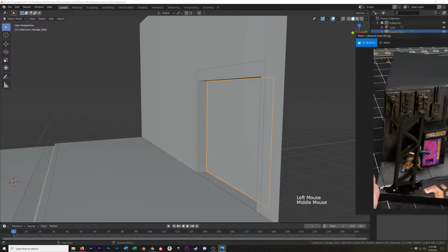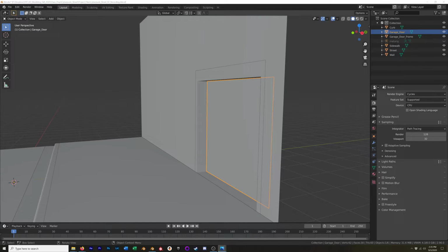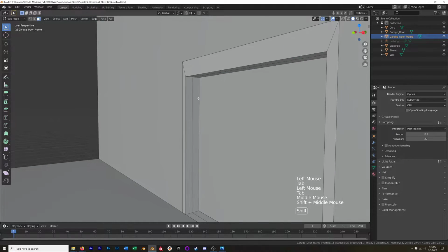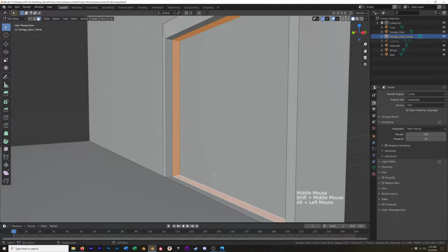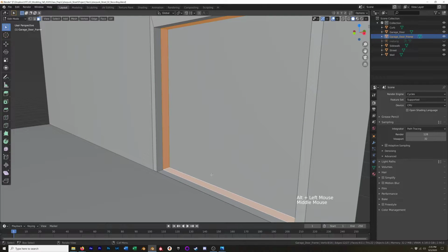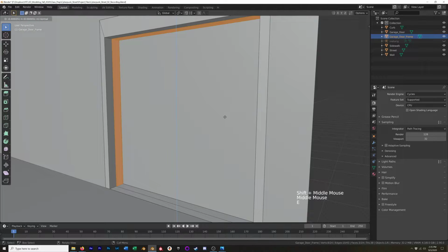And we are eventually going to add this kind of corrugated texture to it, so it's going to have some depth to it. I want to make sure I give the frame some room for that. So I'm going to go back to the frame, and this second extrusion here, I'm going to Option click and select the whole face loop, Shift deselect that bottom face, and hit E to extrude, and right click to keep it in place. And then I'm going to hit Alt S. That's going to scale it along the normals.